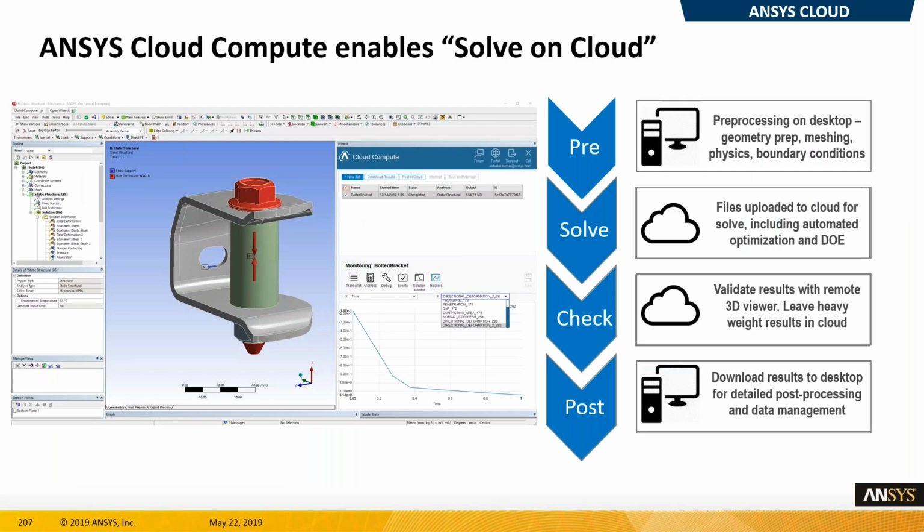The way it works is that you install an ACT app on your Mechanical workspace. This ACT app is then linked up to an Azure database with your account and your prepaid ANSYS units. And then you select your project number, your account number, you select a data center near you, hopefully, and then you submit your project as you would submit it to a local RSM setup.